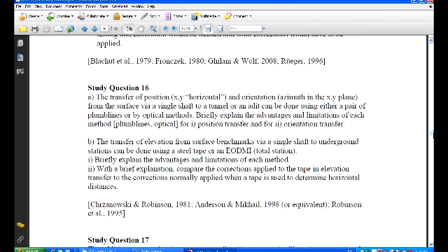The only way we can do that effectively is if the total station is capable of measuring in the zenith. Most high precision total stations are capable of doing that, where the carrying handle will swing out of the way and the machine will indeed measure in the zenith, which means you have to turn off the compensation. The other problem with that is that you then have to transfer the center of the total station to some other point, like a benchmark down below, and that requires a